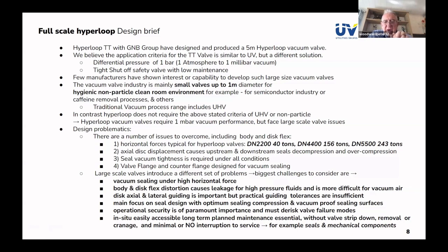Let's say we can get down to 1 millimeter or maybe 2 before you run into other problems of thermal expansion or dust or grit or deposits, which then foul the guides and the valve becomes inoperable. So there are limits, practical restrictions on the guide tolerance.